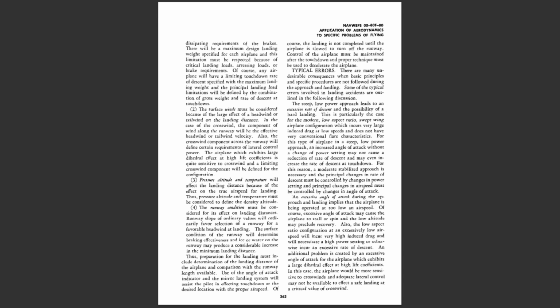Runway slopes of ordinary values will ordinarily favor selection of a runway for a favorable headwind landing. The surface condition of the runway will determine braking effectiveness, and ice or water on the runway may produce a considerable increase in the minimum landing distance.